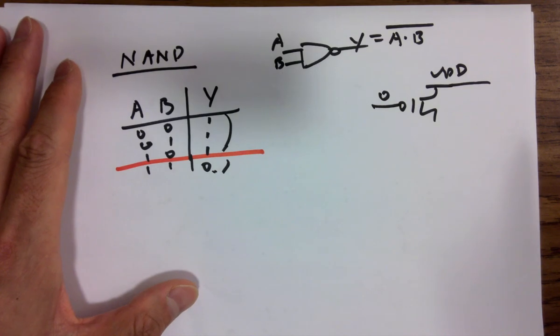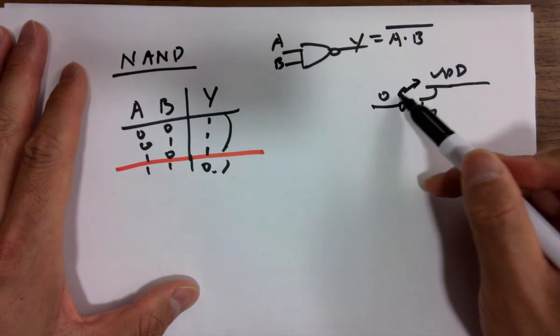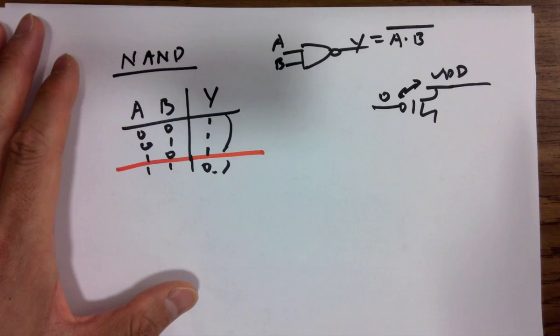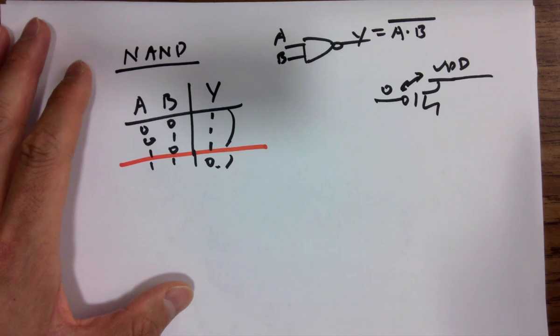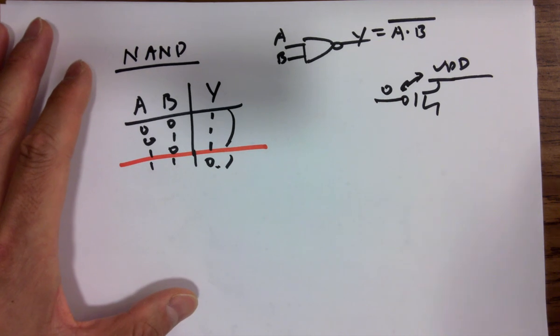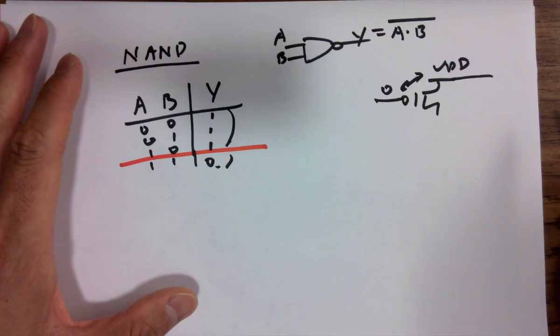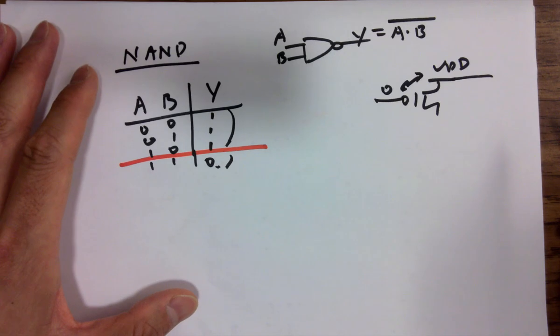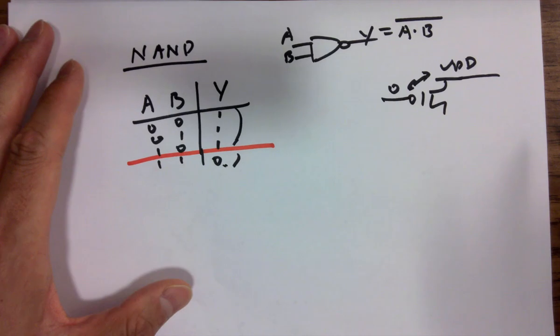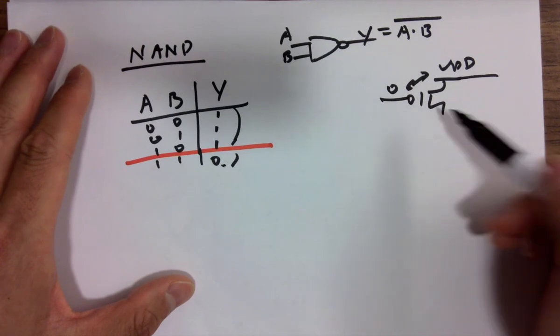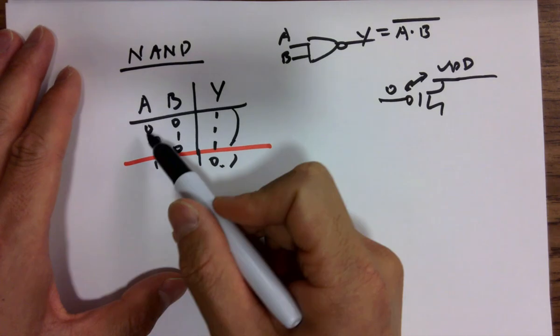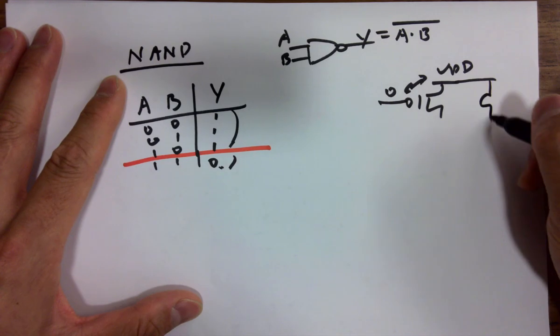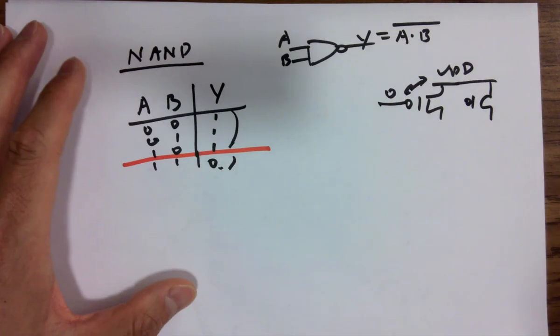We're looking at the VSG, right? So what is VSG in this case? It's VDD, the 5 volts. 5 volts is a lot larger than the threshold voltage for the PMOS, which is 0.9 volts. Is 1 enough to pass it? No, since we have 2 inputs, we need 2 of them, and we would like to put them in parallel. Why is that?